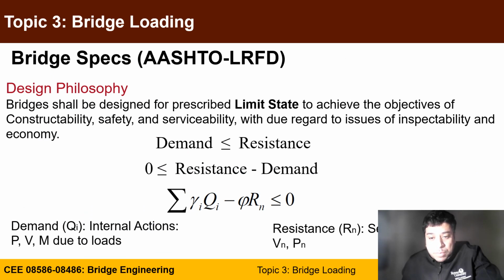So if you go back here to the AASHTO philosophy in LRFD, LRFD is a design philosophy. Bridges shall be designed to prescribed limit states, which we will explain later, to achieve the objectives of bridge design from constructability, safety, and serviceability, with due regard to inspectability and economy.